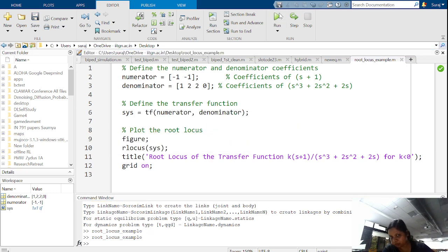Do you see? So we studied the same, no? Here there is a pole at -1 plus j. There is a pole at -1 minus j. Both of them move. Then they meet at the break-in point at minus 1.5. At minus 1.5, one of them moves to infinity, one of them moves to a zero.